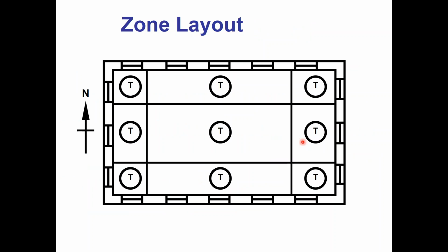From a zone layout standpoint, typically for VAV systems, you'll have one air handling system covering the entire floor of the building, and sometimes even multiple floors. So the interior zones are cooling only. They never need heating. There's no reason for them to need heating. They have no exposure. All of their perimeter, if you will, is 72-degree spaces on all 6 sides of their cube. So they never need heating. They're cooling only, which is why these are 55-degree cooling only systems.